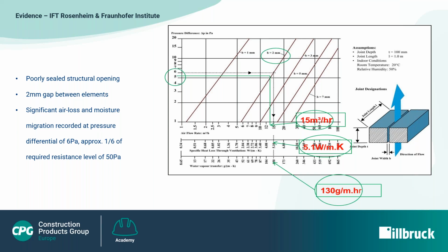The thermal conductivity of 5.1 W/mK demonstrates the potential losses in a poorly or partially sealed facade construction joint, or the tolerance gaps between the glazing frame and the structure. Now, think how many penetrations there may be through a vapor control layer by default, and how many butt joints there are between sheathing boards and insulation slabs on a high-rise building with an SFS infill.